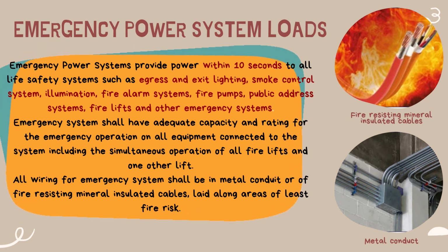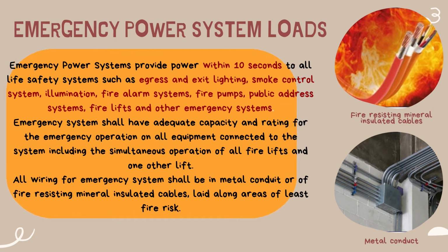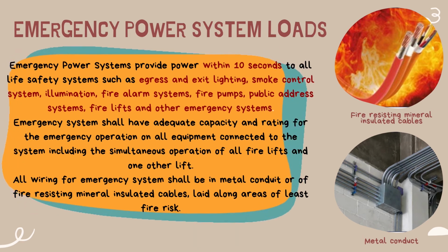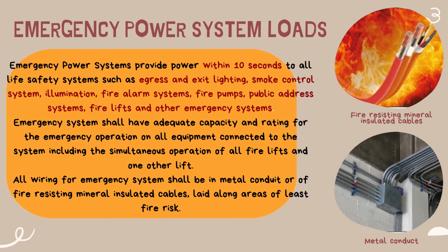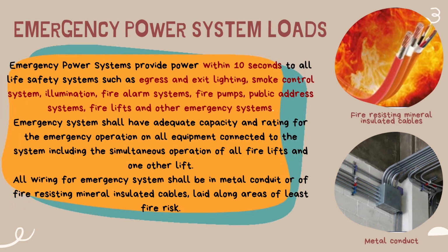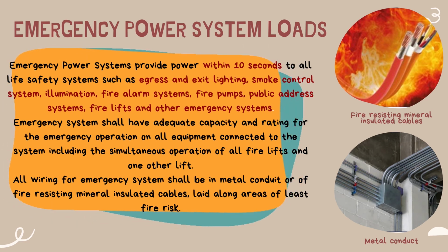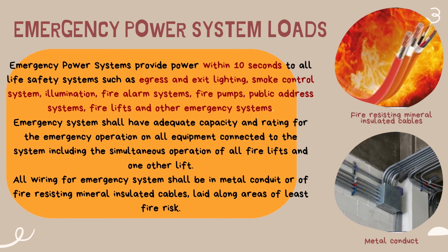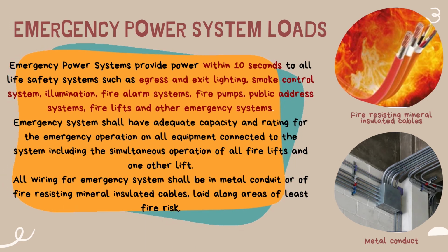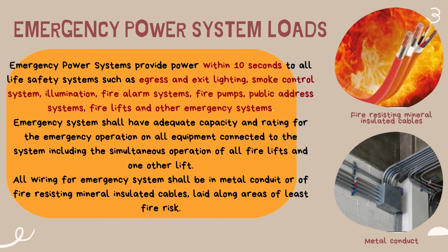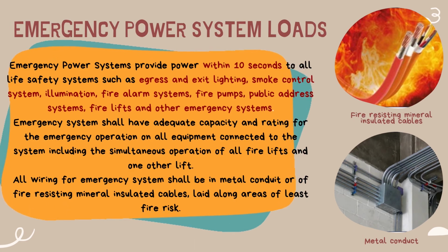Next, the emergency system shall have adequate capacity and rating for the emergency operation of all equipment connected to the system, including the simultaneous operation of all fire lifts and one other lift. Next, all wiring for the emergency system shall be in metal conduit or fire-resisting mineral insulated cables laid along areas of least fire risk. The pictures are examples of metal conduit and fire-resisting mineral insulated cables.